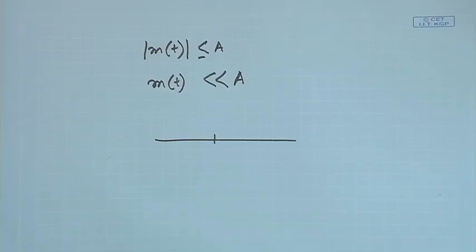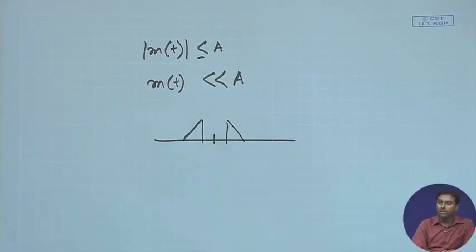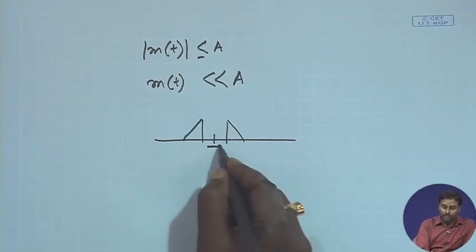So far we have discussed something about single sideband. Now in single sideband we have also talked about that it is only good if you wish to make the transmitter and receiver circuit a little bit simplified, like the Weaver circuit, where you can just use a filtering approach. For that you need to have a spectrum of the modulating signal which is devoid of any component around DC.